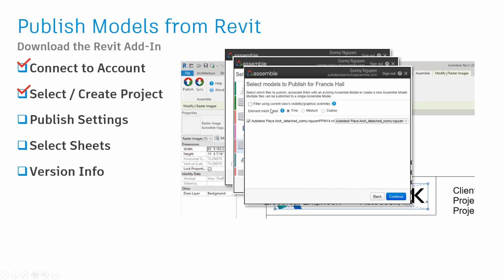We also have some publishing settings here, so we can publish with the filter using current views, visibility, and graphics overrides from the tool you're in. And you can also determine the element mesh detail that you want to publish to. Fine being greater detail, a little bit more detail in the rendering, and coarse obviously is a little bit less.